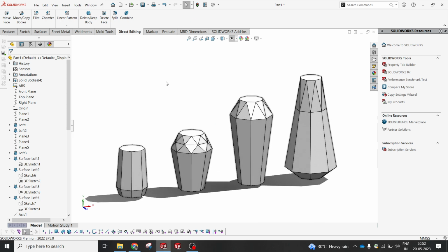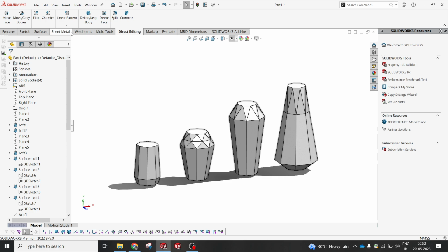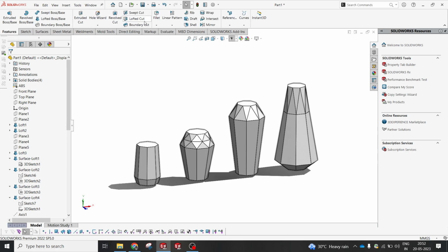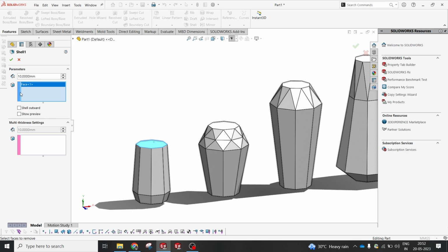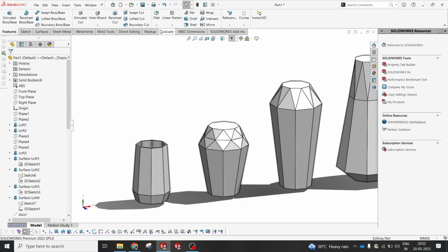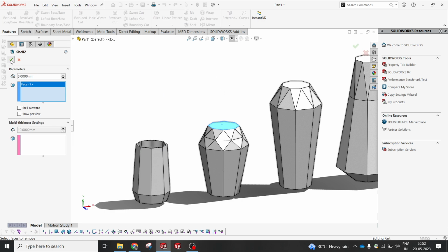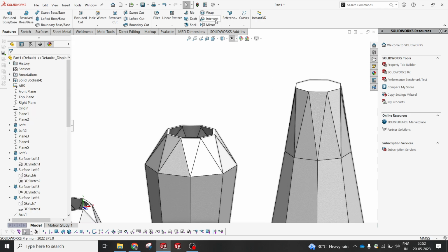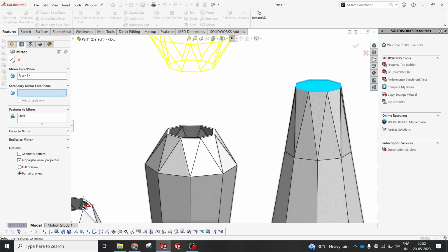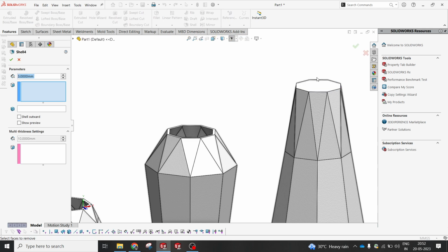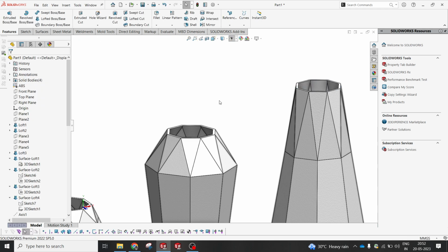Yes. So guys, I also suggest, if you are looking for a thickness, go with a minimum of 3 mm or 4 mm, however you want as per your requirement. So try to do it with all shells. Yes, that's how it looks once you start doing the shell.